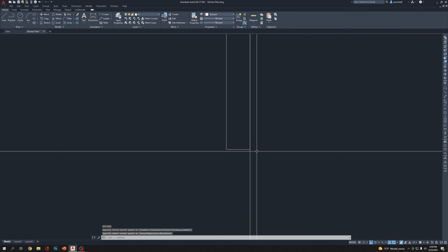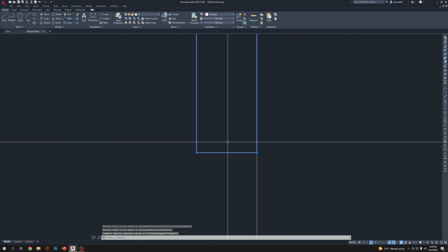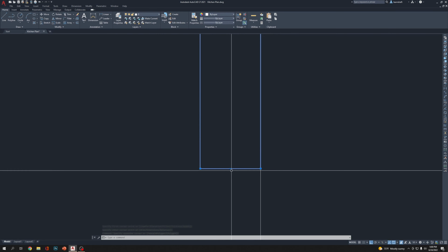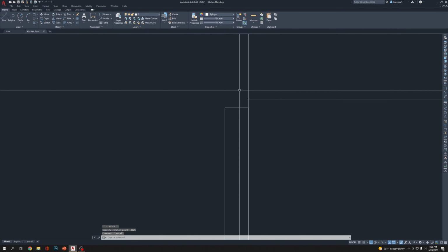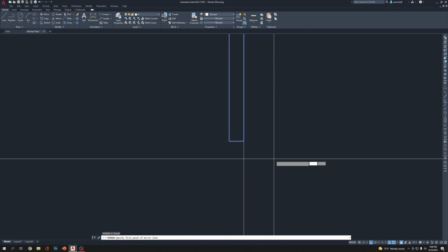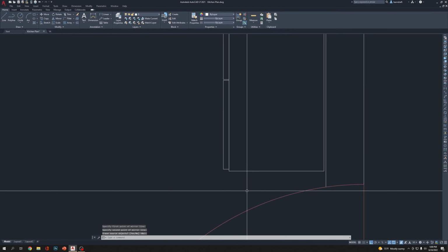Now you need to have at least 0.125 on the center gap between door to door, otherwise they're gonna bump to each other. So I selected the rectangle, click here, go this way, 0.0625, which is the half of 1/8 of inch, enter, and then we are gonna select this one, mirror, and then we have, this is the center point, click, and here you go.